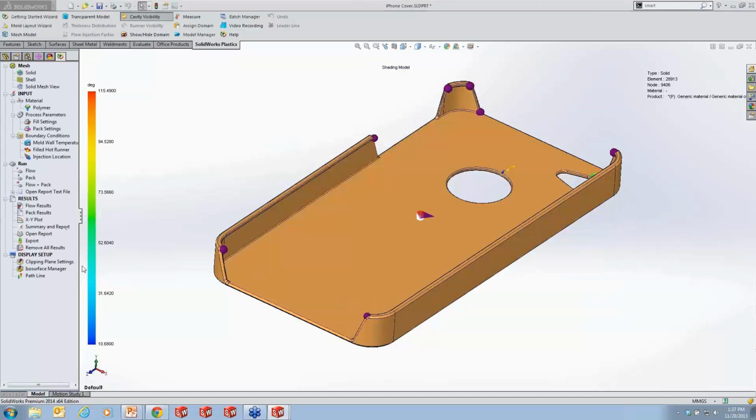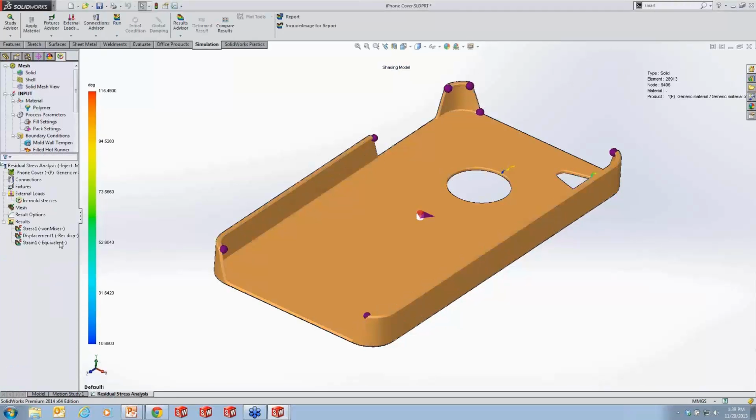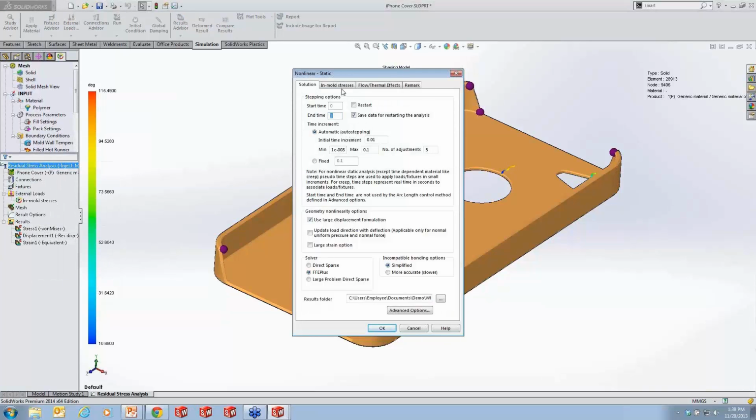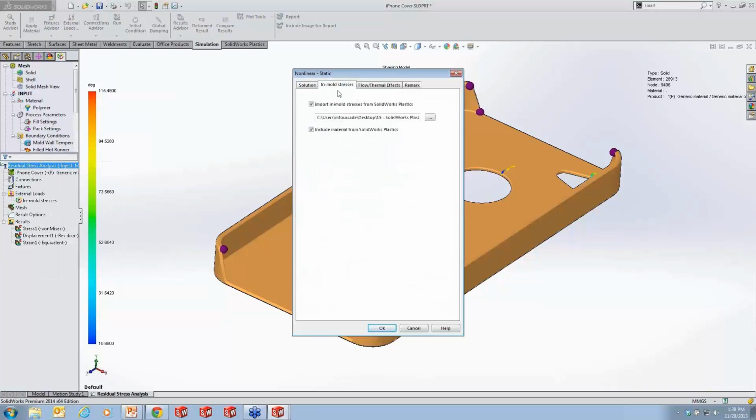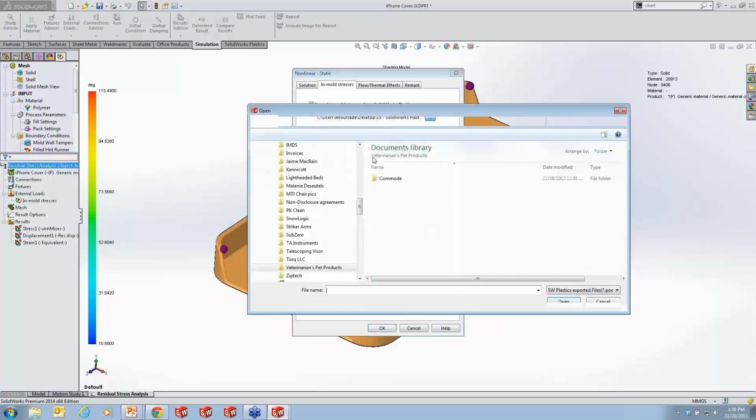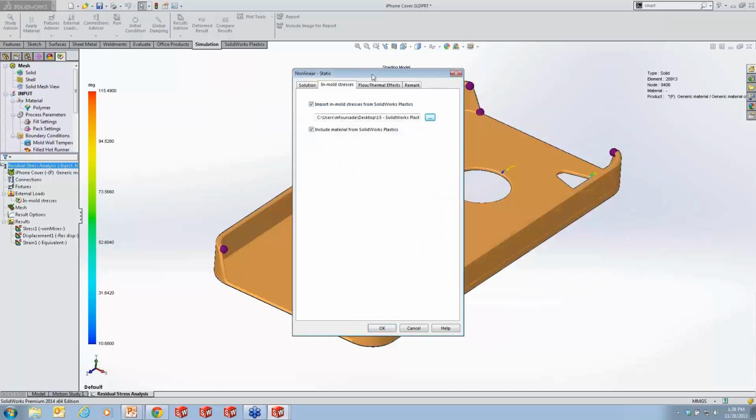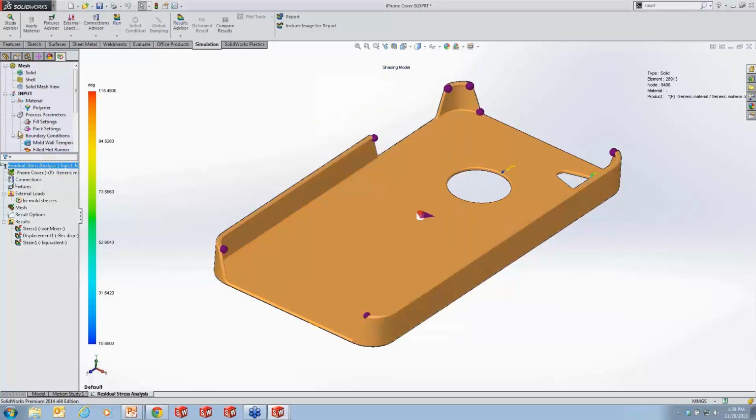If I go into our simulation tool and turn that on, we'll see a study that's already been run here. But basically, when you have a nonlinear solver, you can go into your properties of the study and add in that file that I just had. It's in a different path than where it was pointed there, but I have that file already imported and ran.